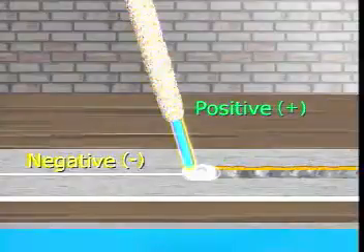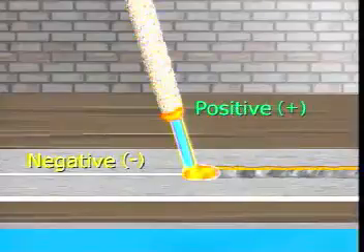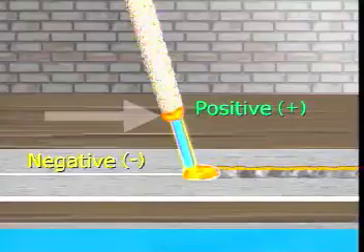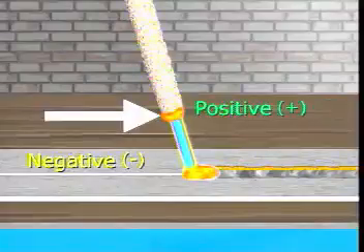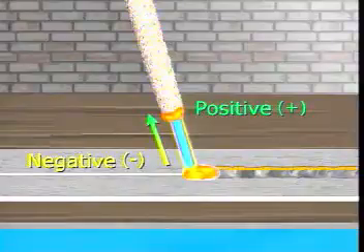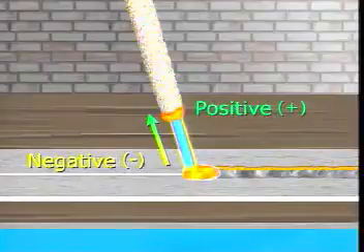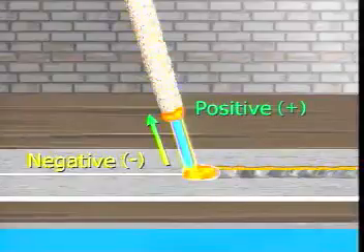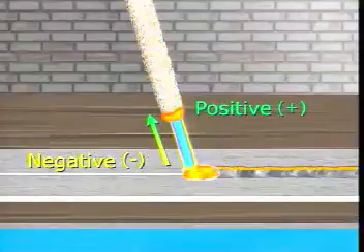Now, during arc welding, heat is generated at both ends of the arc. So both the welding machine's electrode and the metal being welded become extremely hot. However, the conductor at the positive side of an arc gets hotter than the conductor at the negative side. That's because electrons flow from negative to positive, and the collisions between electrons and the positive surface generate heat in addition to the heat caused by just the flow of electrons. Also, the action of electrons leaving the negative surface tends to have a cooling effect on that surface.